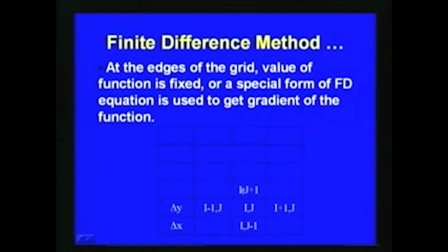There are also variations with respect to space and with respect to time; there are a number of methodologies for the finite difference method available. Essentially, what we are doing here, as already discussed, is between 2 grid points we see the difference, say the gradient, and then we try to approximate the governing equation, here the Navier-Stokes equation, write that difference equation, and then solve it with respect to the known values or the boundary conditions. So, this is the finite difference method.